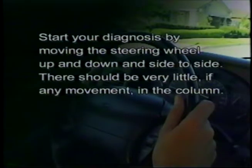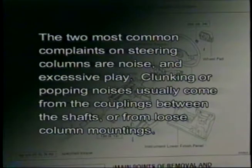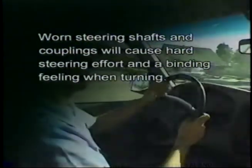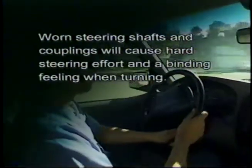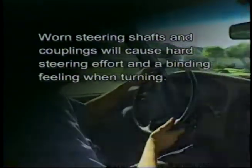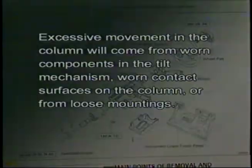Keep in mind when troubleshooting steering columns that the two most common complaints on steering columns are noise and excessive play. Clunking or popping noises usually come from the couplings between the shafts or from loose column mountings. Worn steering shafts and couplings will also cause hard steering effort and a binding feeling when turning. Excessive movement in the column will come from worn components in the tilt mechanism, worn contact surfaces on the column, or from loose mountings.